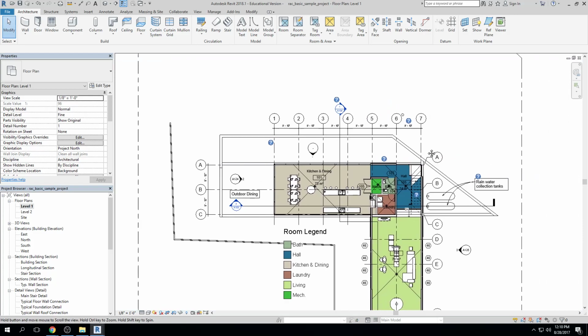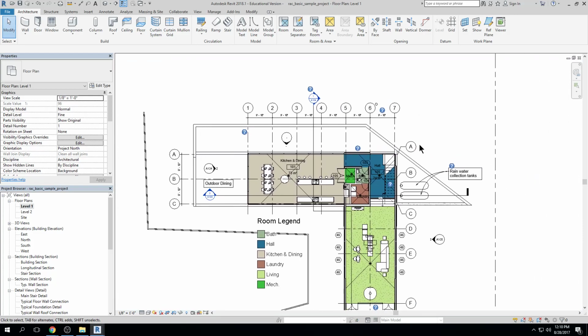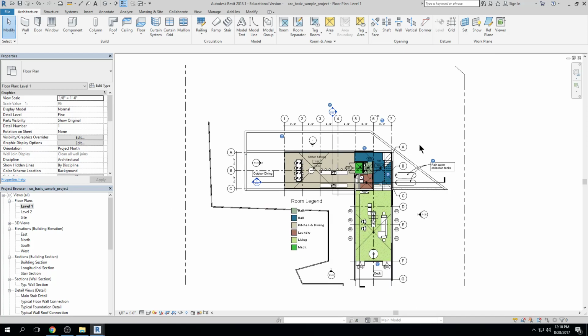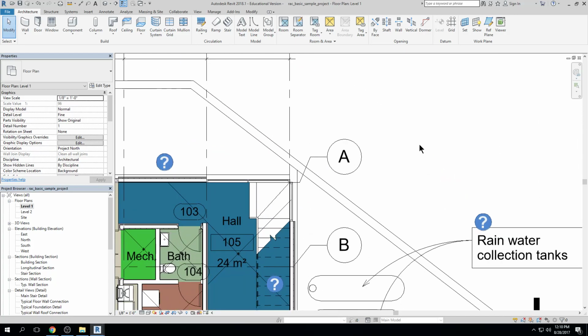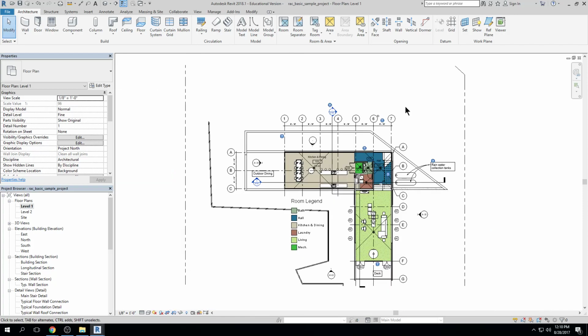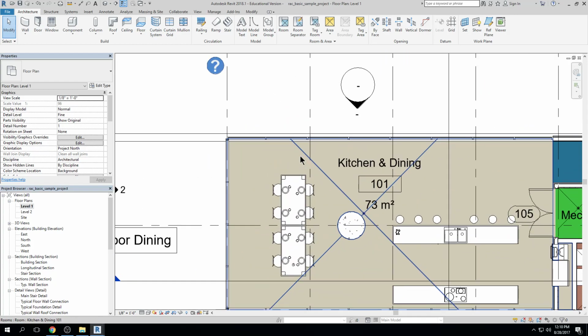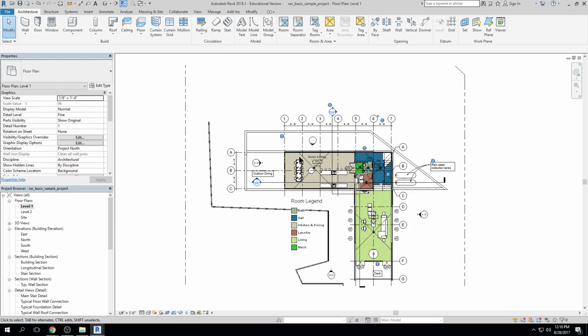All right, another little shortcut, ZE, zoom extents. So if I'm zoomed very far in and I need to come out to view the entire picture, ZE, zoom extents. I can also use my middle roller button and double click the middle roller, twice very fast, same as AutoCAD, to zoom extents. That brings me out to the extent of the drawing, which is the extent of the crop region.